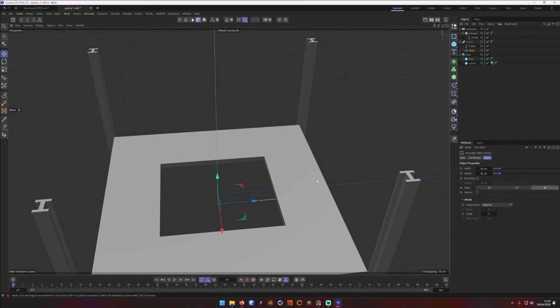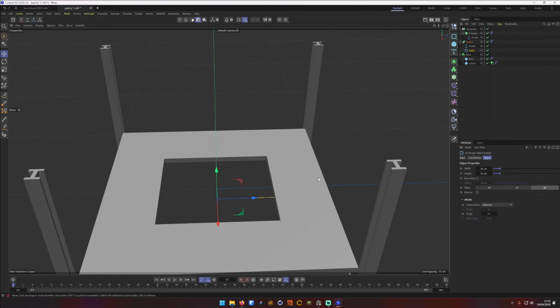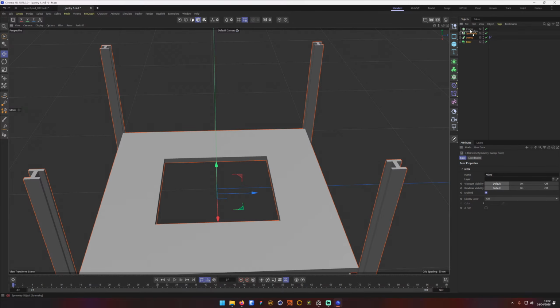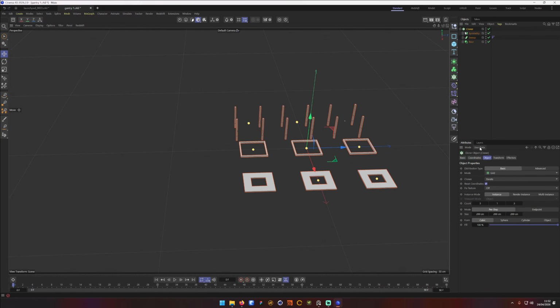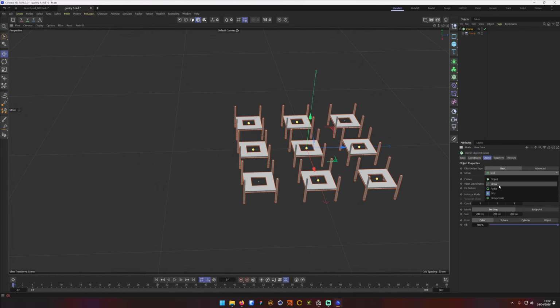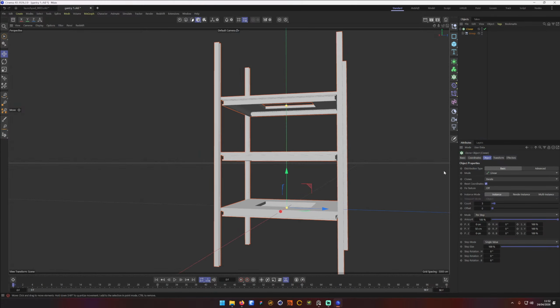Okay, so there is our floor, and then what we're probably going to do, I think the best thing to do for a handrail, let's look at this quickly. So what we can do is go into replicator. No, that's a subdiv, that's the wrong button. There's a cloner. I keep saying replicator, so cloner, right? Okay. So what we're going to do quickly is Alt G, there we go, and then we're going to do that. Cool. Cloner, we're going to change this to linear. There we go. Cool. So this is our basic setup.